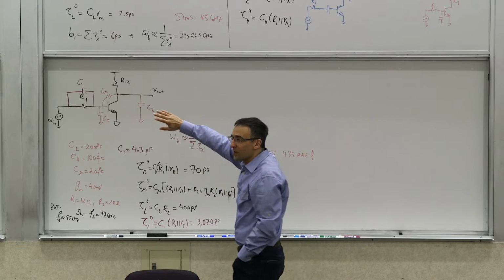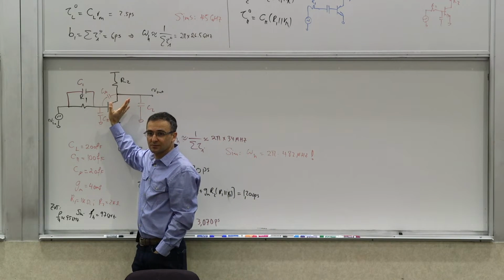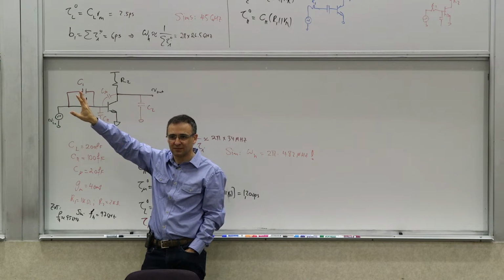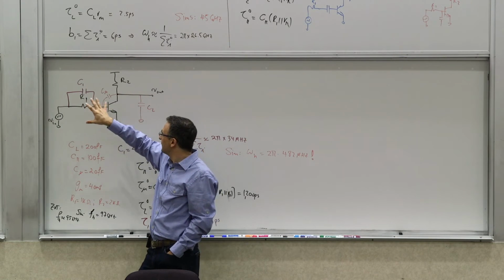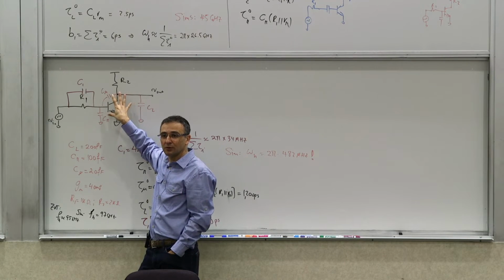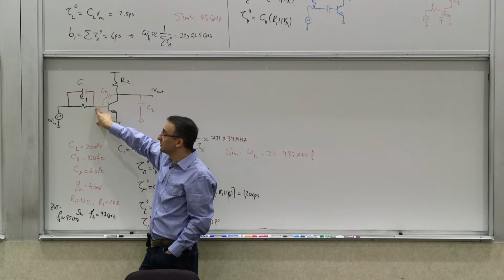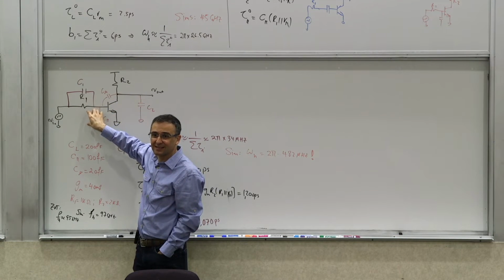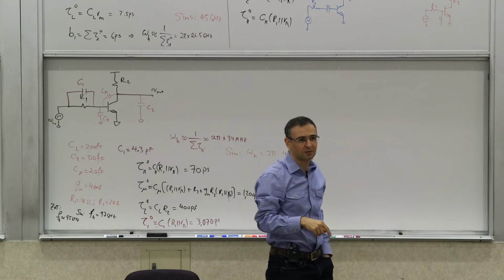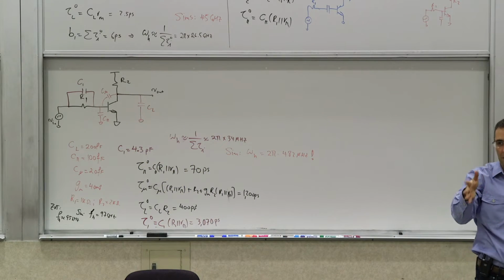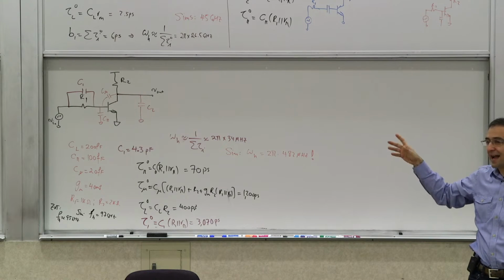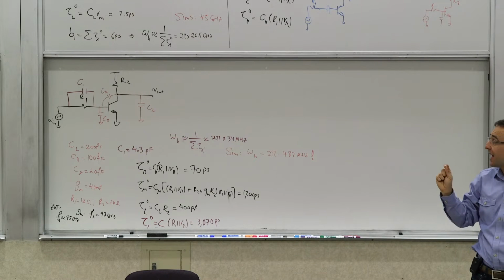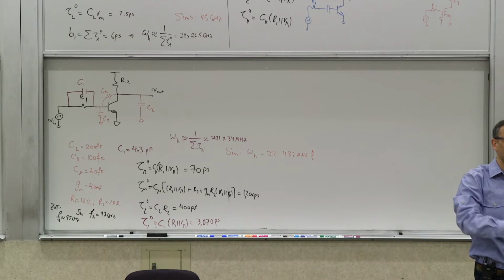You remember, this circuit without this guy had two poles and a right half plane zero that was at pretty high frequency. It had one dominant pole, if you remember. The dominant pole was at the input, which is basically this resistance with the Miller equivalent capacitance at the input. That gave you a capacitance there in parallel with R1 parallel with R pi. That gave me a first pole. So how do you think I chose the value of C1? Where did I put my zero?